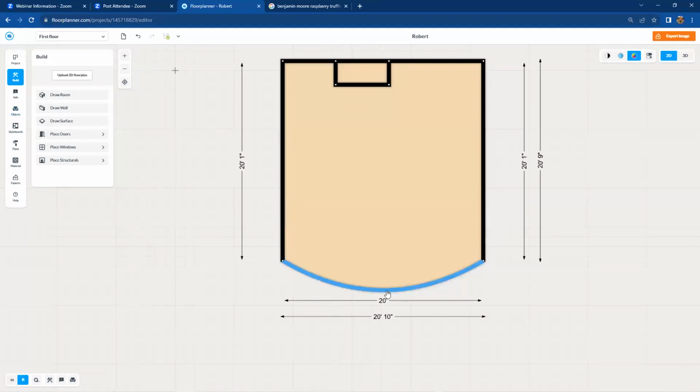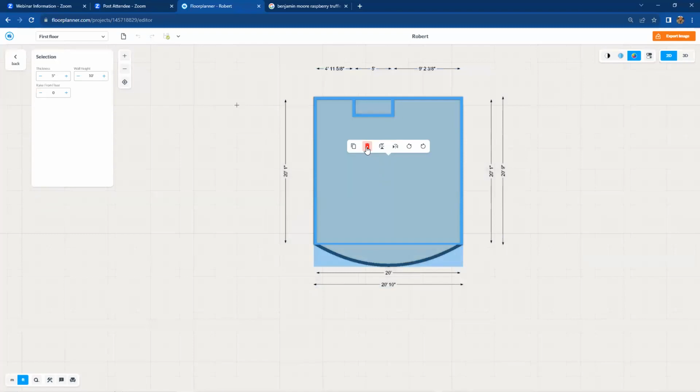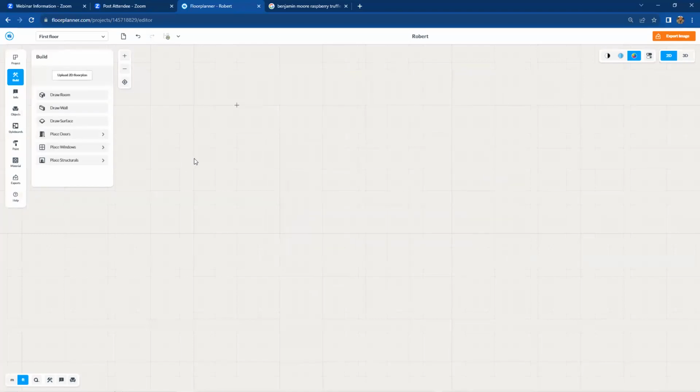And also it comes in really handy for an angled wall because you can just trace it and have no problem with it. To do so, we're gonna go ahead and trace the background. I'll hold my shift key and go ahead and select this volume again and delete it. So let's put a background to trace inside this project.